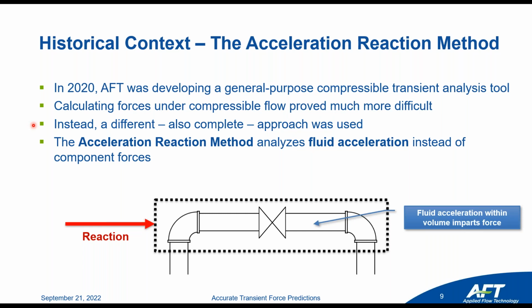What's the control volume? The component reaction method essentially did not draw the control volume outside around the pipes. It drew it essentially on the inside of the pipe, around the fluid, and that becomes the previous method that we use in Impulse called the component reaction method. But Scott realized that if we drew a different control volume, we could actually estimate the forces that are imbalanced to the fluid transient differently.